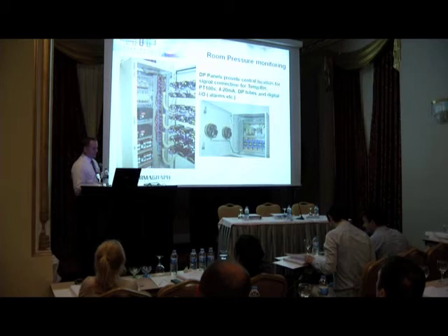As long as you've got a positive pressure of 15 Pascals, that's fine, and your alarm limit is set at 15 Pascals, but the real problem is when you get a negative pressure of, say, 5 or 10 Pascals. That's when you've really got to look at what's been going on in that room and potentially what the cause and effect would be.